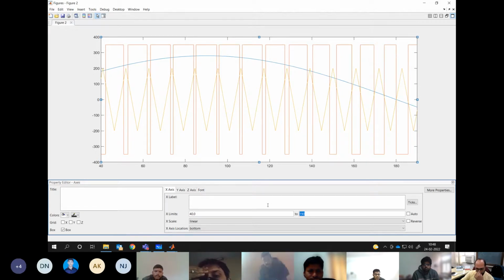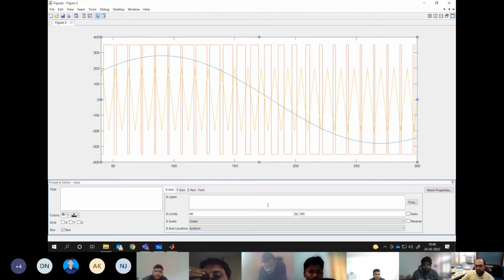So now if you go up to, let us say, 270, or let me write 300, then again you see that the positive pulse width has reduced to a very low value, close to 270. This is around 270. The positive width is very, very small. The negative has increased. Correct? This is the meaning of pulse width modulation. You can see the variation, the gradual change in the positive pulse width or negative pulse width, whichever is comfortable for you. It is gradually increasing up to the positive peak.